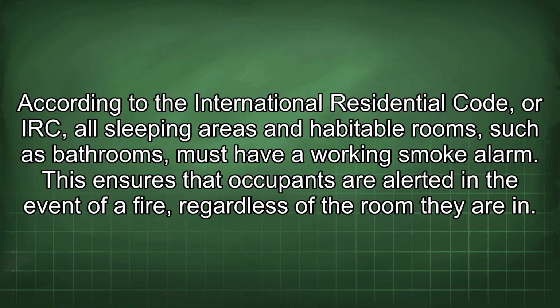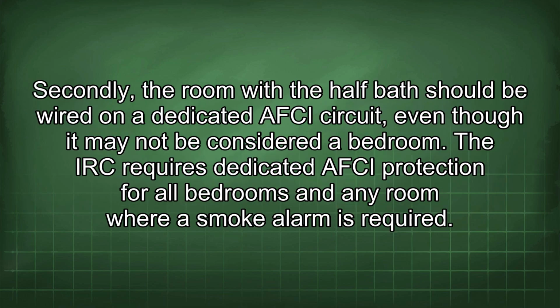According to the International Residential Code, or IRC, all sleeping areas and habitable rooms, such as bathrooms, must have a working smoke alarm. This ensures that occupants are alerted in the event of a fire, regardless of the room they are in. Secondly, the room with the half bath should be wired on a dedicated AFCI circuit, even though it may not be considered a bedroom.